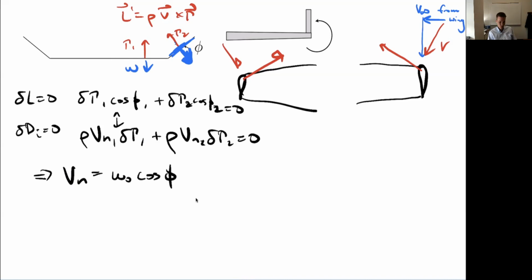Specifically, if we look at a vertical winglet, phi is 90 degrees in that case. And that says that for optimal loading, the net normal wash of the winglet should be 0. This is not net 0, right? So there's an induced velocity that is non-zero. So actually what we would like for optimal loading is for the winglet to look something like this, right? So I've got still, of course, V infinity, I'm flying forward. And I still have this induced velocity from the wing, that still exists.